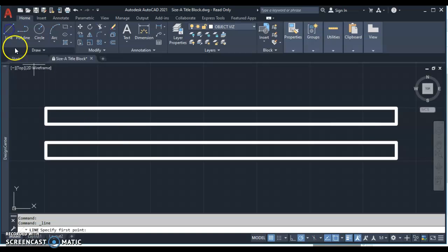Using the line tool, come down here, and I want you to mouse over the end point of this. And from the end point, I'm not clicking on anything. I'm just simply mousing over it until I get that little green snap. I'm going to pull out along the line, and as I do, you see the word extension appears, and there's a dotted line that starts to kind of draw itself, an extension line. What I'm saying is I'm using the end of this part as a reference,